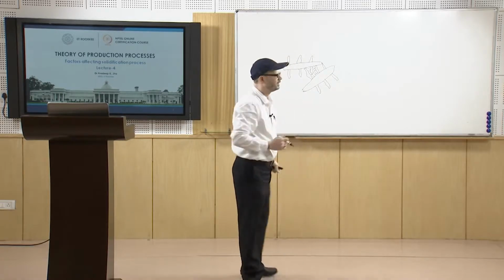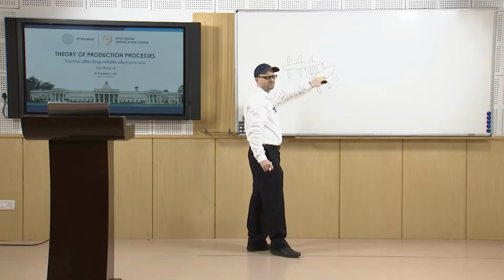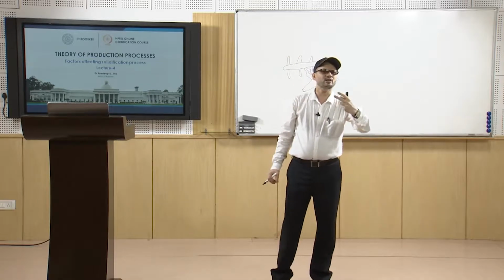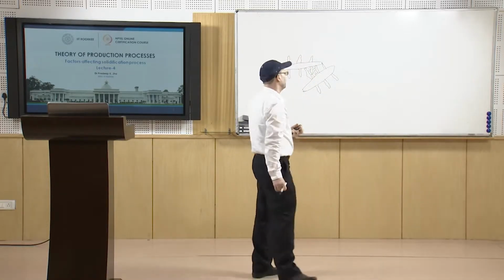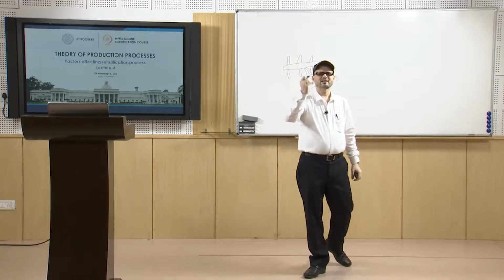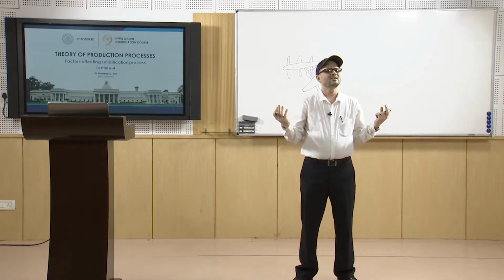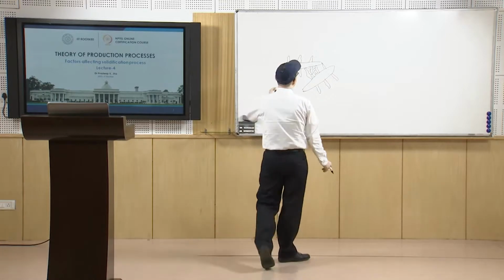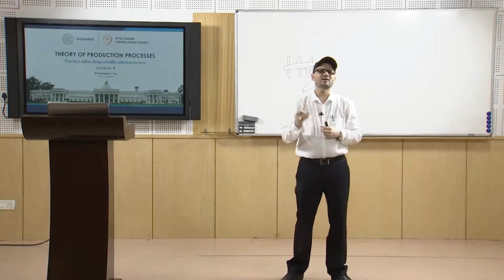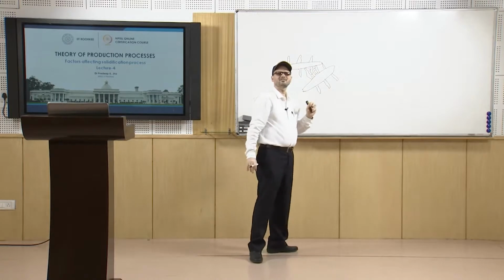In casting, as the metal solidifies, since the density of solid is more than that of liquid, there will be shrinkage of the liquid metal. The void which is created is compensated by an extra reservoir known as a riser, or any extra path by which extra metal can come and fill that point where the void is created.